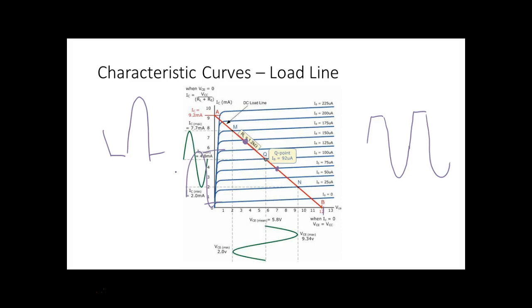But as long as you don't overdrive it, understand, even though it's biased toward saturation or cutoff, all that's going to do is you just add another stage. So you go through more stages. Does that make sense? Still, your stages are relatively cheap compared to trying to bias this thing right in the center. That's a good point. Yeah, you're right. But couldn't you imagine looking in the amplifier and seeing 15 resistors in series to get a 1,232.3 ohm resistor?